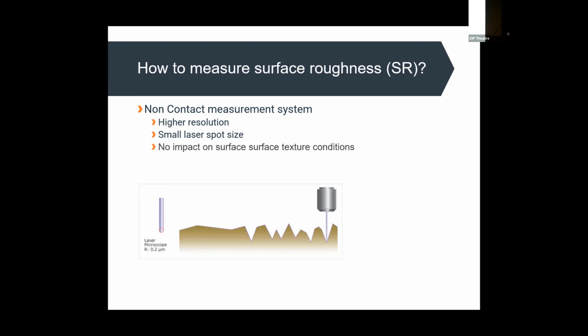The non-contact measurement system, using, for instance, a laser, will give you better resolution and will not affect the surface texture conditions either. But the problem with a laser is that the surface finish will, for instance, cause some refraction and other problems.